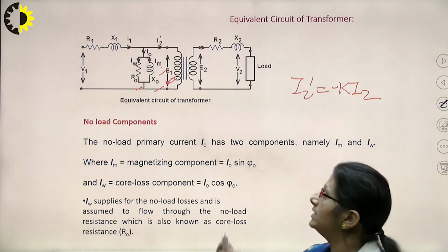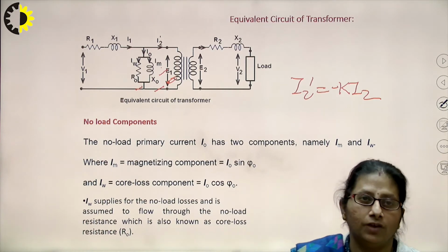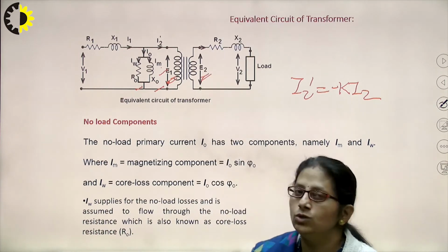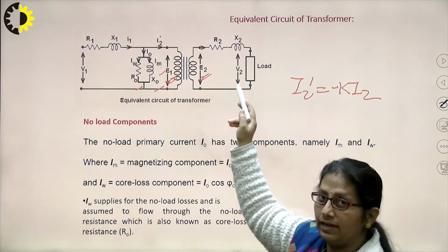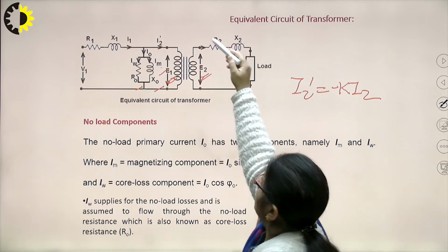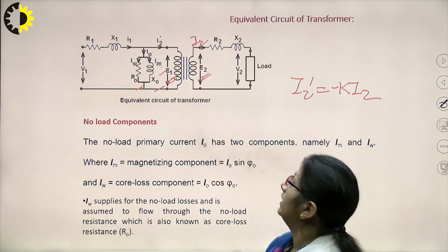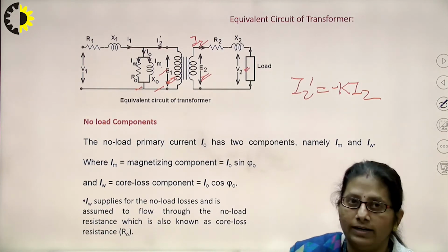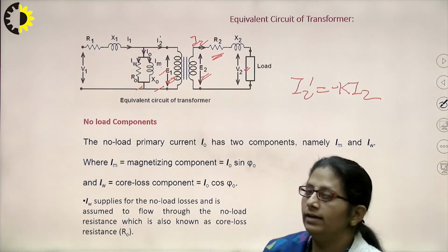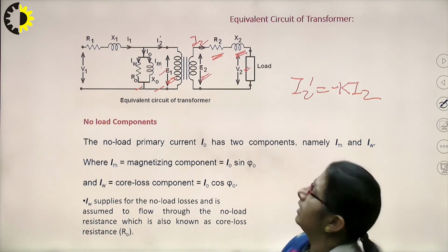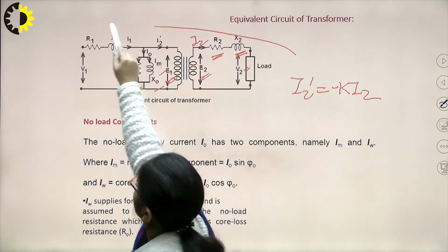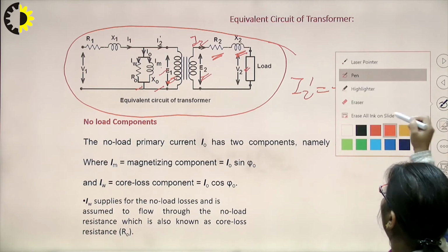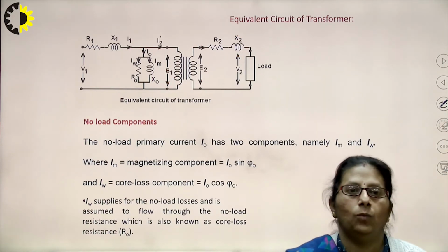Coming to the secondary circuit. When the same flux links with the secondary, I will have an EMF produced in the secondary, the RMS value of which I used to call E2. The load is connected to the secondary, so I will have a current flowing in the secondary, which I used to call I2. The terminal voltage across the load I am calling V2. The secondary winding resistance needs to be represented by R2, and the secondary leakage reactance by X2. This completes the exact equivalent circuit of the transformer, without referring any of the values. The values are not being referred anywhere.